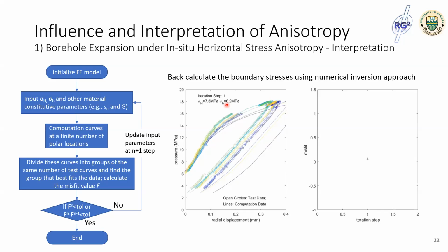And from what I know, there are also great difficulties in using a self-boring pressure meter to interpret the in-situ stress, because no matter how perfect the borehole you drill, it will be more or less affected by disturbance of the borehole wall, which is the same situation as in this test. So we didn't do that test, but I'm afraid the self-boring pressure meter could not provide better results.